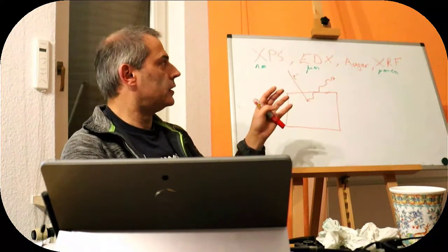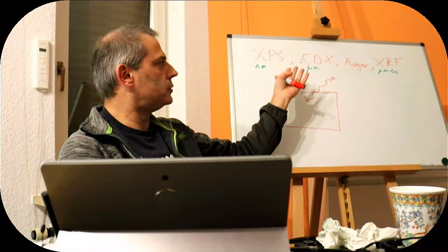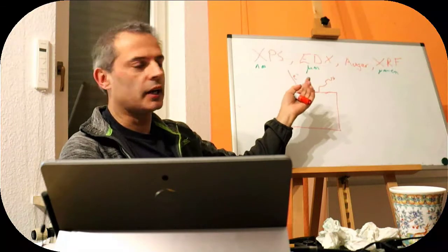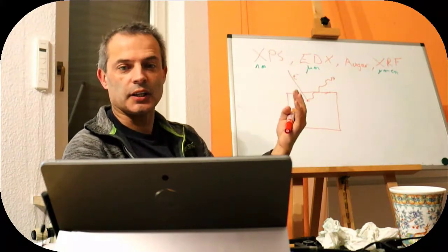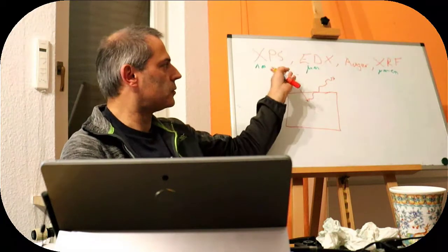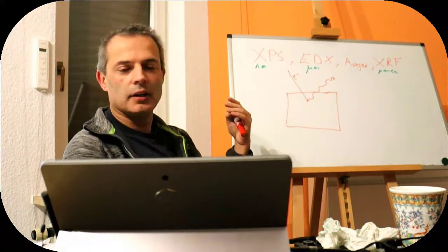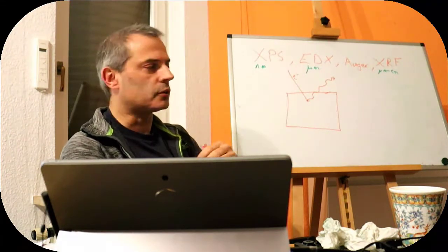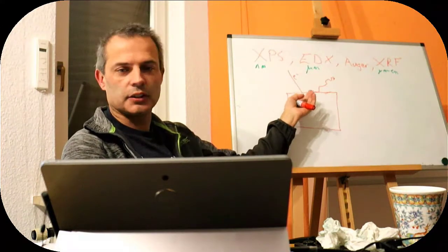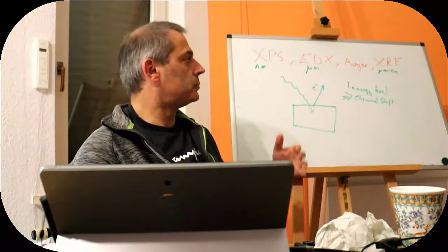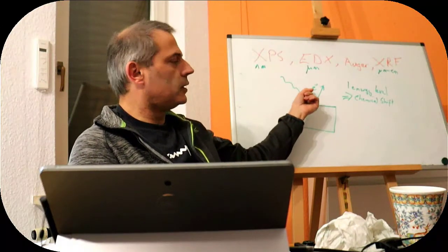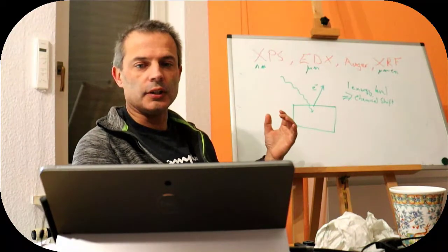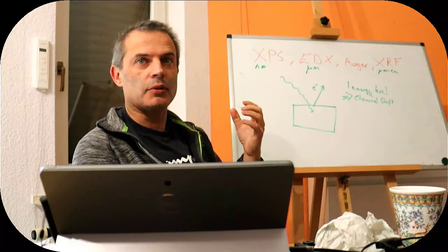In fact, the reason that the electron microscope that we're using to do this has a comparatively better surface sensitivity is that the electron that we look at, the secondary electron that bounces off, can't escape as easily as the X-ray. So although the electron beam passes into our substrate, the one that we're looking at, the one that's escaping, either backscattered or secondary electron, has a lower energy and therefore it can't escape so easily. So we come to the depth sensitivity. This comes from the low energy of the electron that we're going to measure here, because it's not moving very fast, so it can't escape from very deep, and so we only get nanometer depth sensitivity.